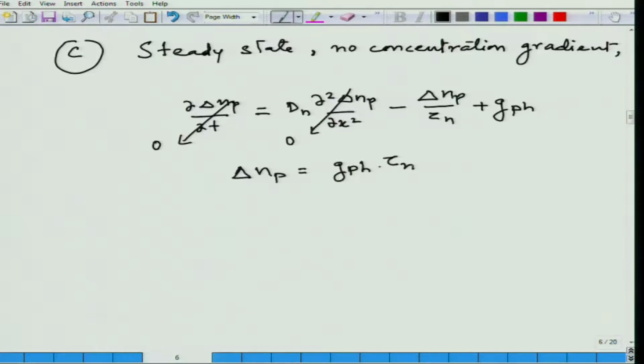So, this is the excess carrier I generate. This is a very simple problem which has a very simple physical interpretation. What am I saying? I take a semiconductor in which I am looking at the change in the carrier concentration. Let's say this is a p type semiconductor. I am looking at the carrier concentration of electrons in the p type material, and I am shining light on it. It is creating certain electron and hole pairs at some rate per second, and I continue to shine.